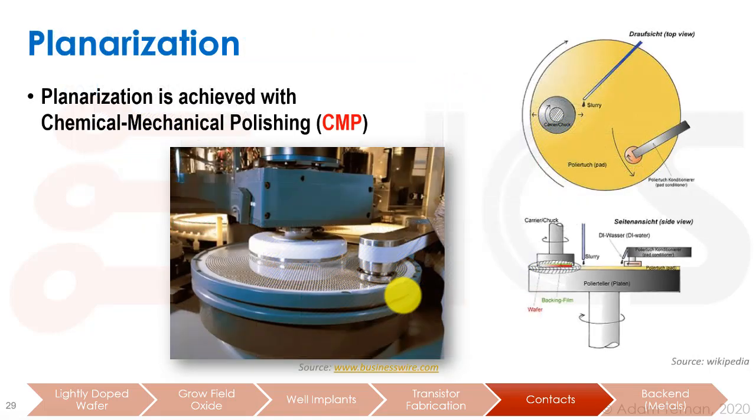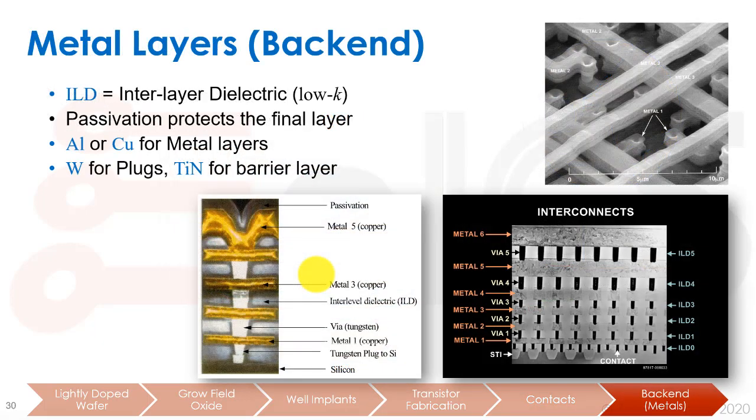Okay, I just mentioned before planarization with the chemical mechanical polishing, or CMP process. Here you can see a picture of the CMP process, and you see that this big wheel turns around with both the abrasive material and some fluid on it, and that's how it planarizes the wafer, and it makes it really shiny and nice and mirror-like. It does it really well and perfect.